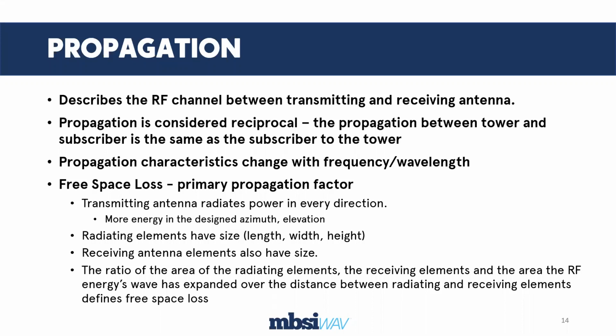Propagation characteristics change with the frequency. So in our case, as we go up in frequency, our propagation loss gets higher for the same distance. As we get higher in frequency, maybe moisture in the air begins to make a difference. As we approach 30, 40, 50 gig, 60 gig, oxygen in the air can make a difference in the propagation characteristics. There's many things that can happen here. I don't want to talk about that too terribly much now. That's a topic of maybe another tech talk here, but nevertheless, it is different as we change frequency.